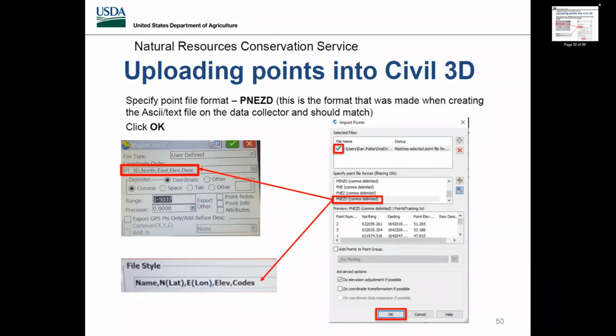Yeah, GPS kind of does that, and I've run into this too, John. Not to the point where it's 7 foot off, but 4 foot has probably been our max, at least in Cecil. But 7 foot is a pretty significant amount. If you're using a base station and GLONASS, you're not using RTK, it's not being fixed by OPUS and you're not sending it off, you could show discrepancies like that. I remember when we first got our GPS, we didn't have discrepancies that large. 7 foot just seems really extreme. Yeah, that's out of the norm. I've never seen one that far. Maybe the satellites were bad that day, or something was going on.